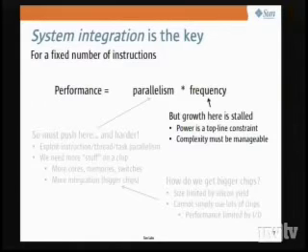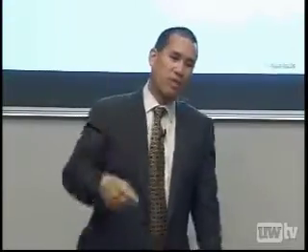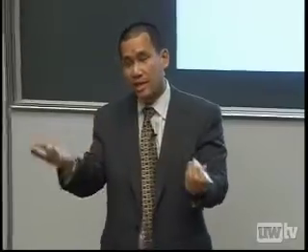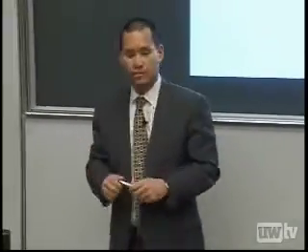In addition, if I wanted to push frequency, I'd better get gate delays down, seconds per gate, and that's hard. And I better get gates per cycle down. Getting gates per cycle down means building what are called short-tick machines, machines that clock at 10 FO4, 10 gate delays per cycle or faster.